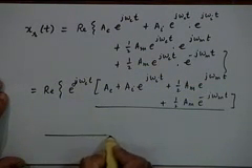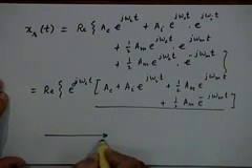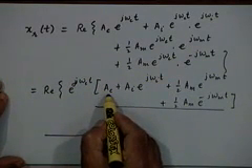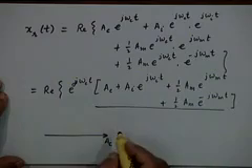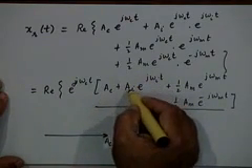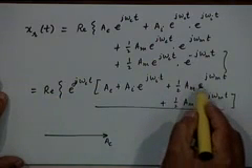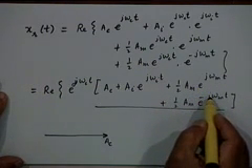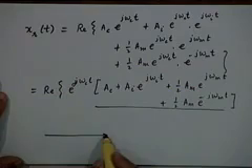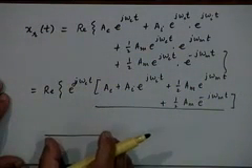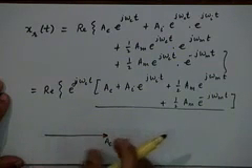You have this carrier phasor with amplitude A_c. Then you don't have this, because at the moment we are not considering it. We have these two sideband phasors with respect to this carrier phasor, which is actually rotating at omega_c, but if the whole frame is rotating, it will appear to be fixed.